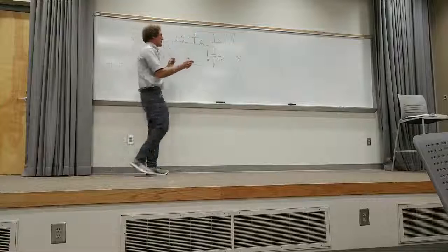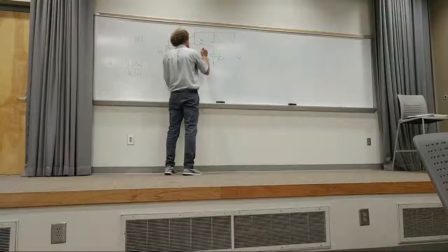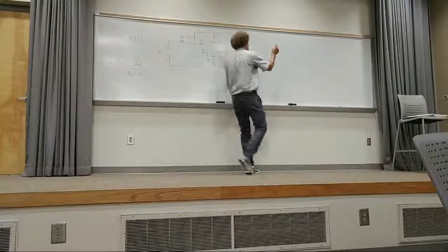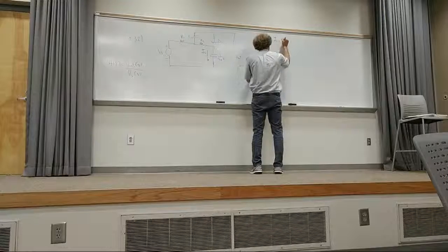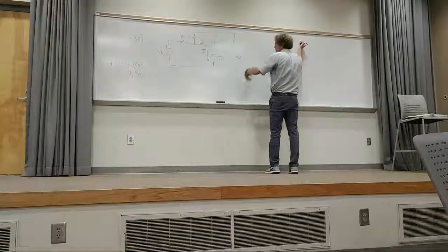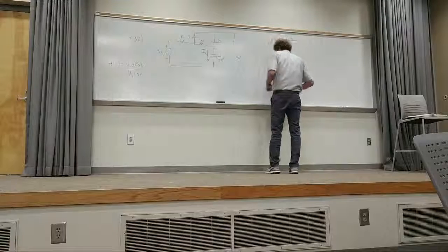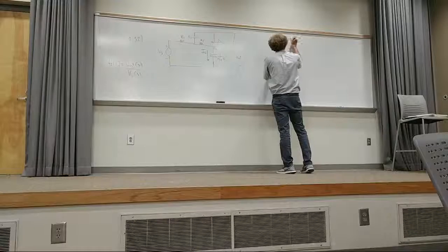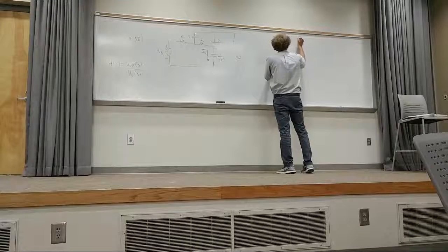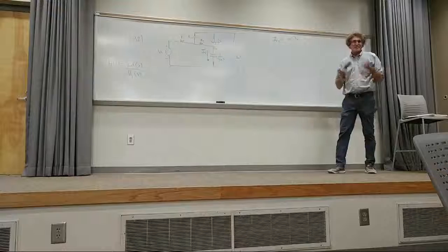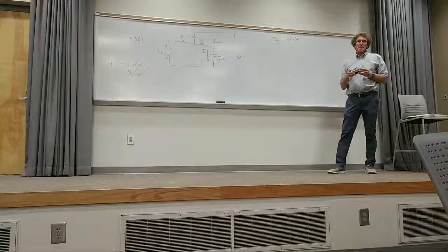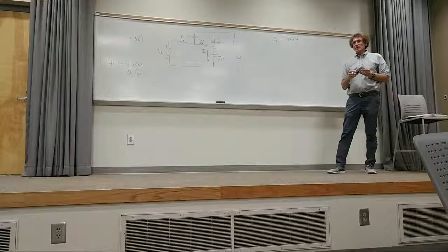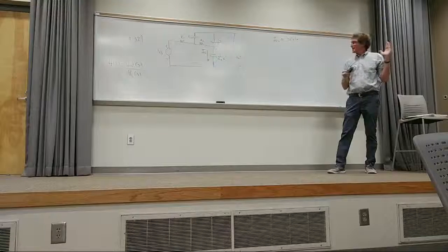I'm going to go ahead and label this IC2 for now, and I'll put IC2 here. It's simply going to be V out divided by 1 over C2S, so it's really S times C2 times V out. Do you agree with that? Because it's 1 over SC, right? Please take a look at that. I don't want to run through anything. Are you with me on this? All right, so that's IC2.